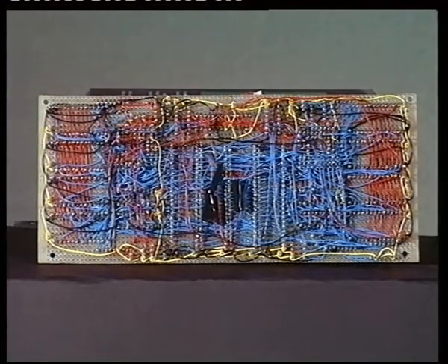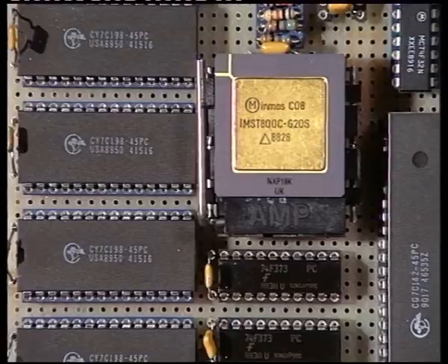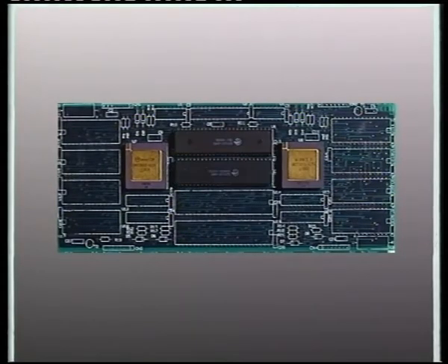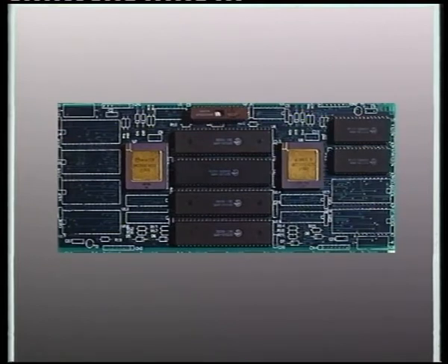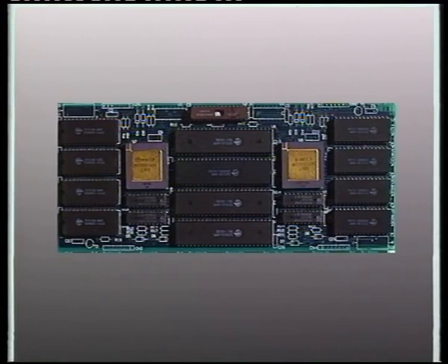The project began by placing two transputers on the same board and developing an interconnection technique that does not use their communication links. As all 8 links are therefore available for connections to other processors, the computational power of the new unit is theoretically double that of a single transputer. These characteristics are achieved by means of shared memory used as a communication channel between the two processors.